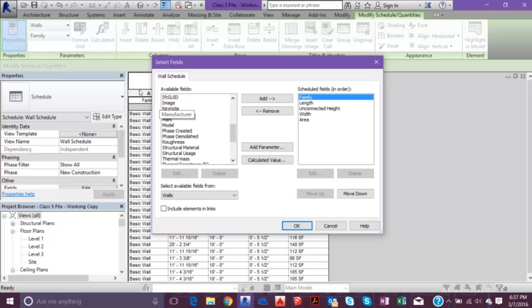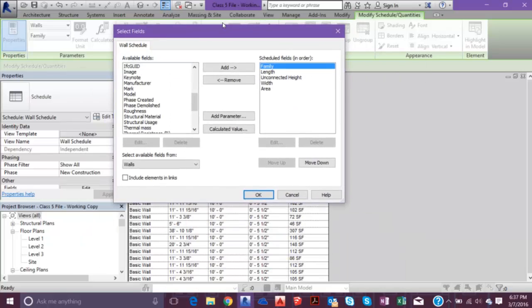Again, with our keynote tag, if we were to add a keynote to a certain material in here, it'll again put this into the schedules. Then we can easily estimate if we're looking for a certain listing of a certain part of the wall. It'll easily correspond. Again, if you want to do databasing with your BIM model, you have a database of those materials, and you have pricing, and you have benchmark pricing off of it. You can connect it to that.